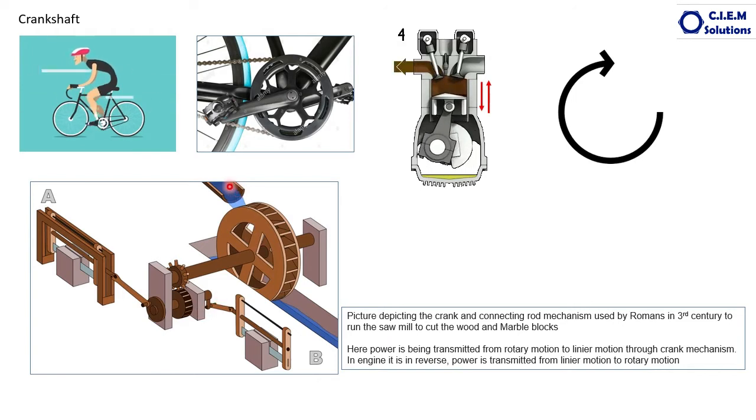Now when water flows down by gravity, it falls on the blades and the wheel is rotated. Along with the wheel, the shaft and the gear are rotated. These are all rotary motion. Again this gear is rotated, whereas this crank, which moves circumferentially around the axis of the shaft, will push and pull. When it comes here, the distance from here to here is different. When it comes here, again the distance is different. It pulls and pushes this connecting rod.